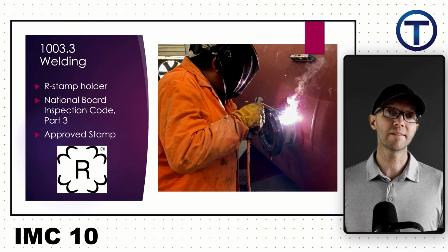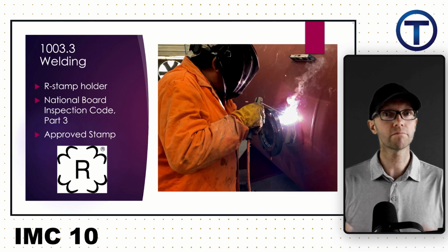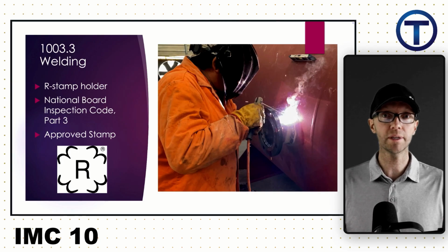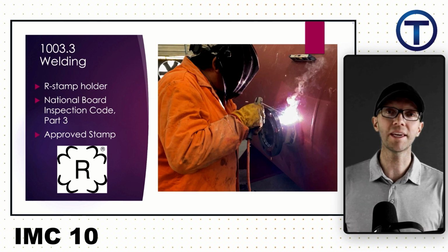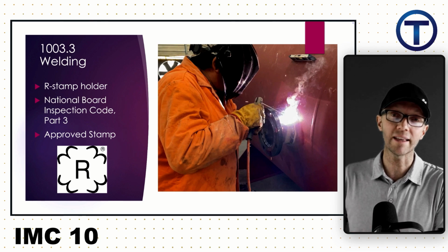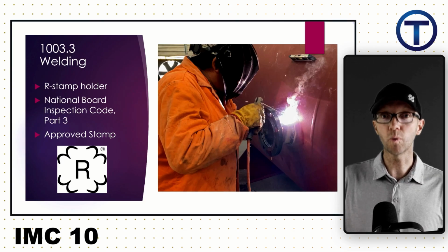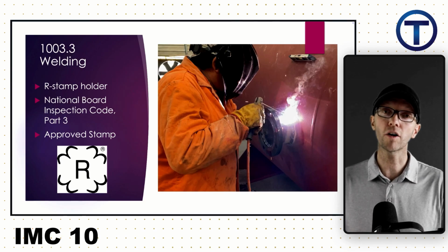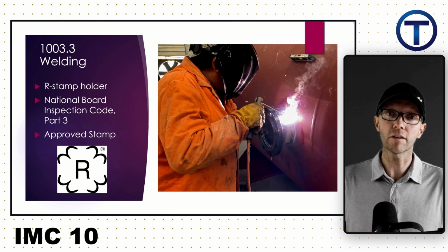1003.3 gives us a specific standard for those pressured vessels. Many pressure vessels are just metal that's been shaped and welded together. And that welding is going to be the only thing keeping that pressure vessel from exploding. So it also has to meet a high standard. It's called the R stamp. Those who are working on welding on these tanks have to be an R stamp holder, or they've met that approved standard in their skill at welding.